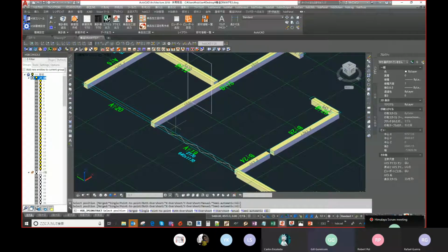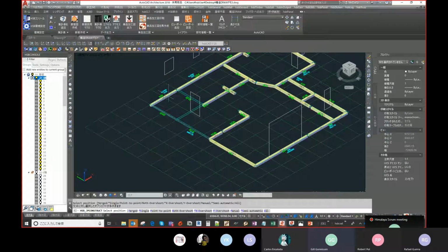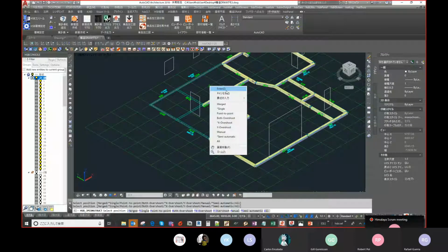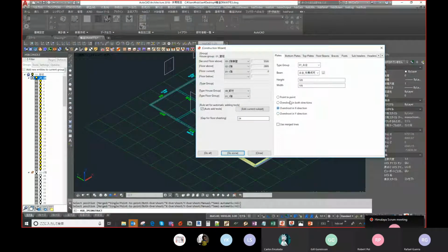Okay. So you can imagine if you have to draw this with the normal timber function, it requires a lot of time. So here it is just sufficient to, in the area you see it's highlighting where it has found a logical position to position that type of beam, and with one click it just positions it.